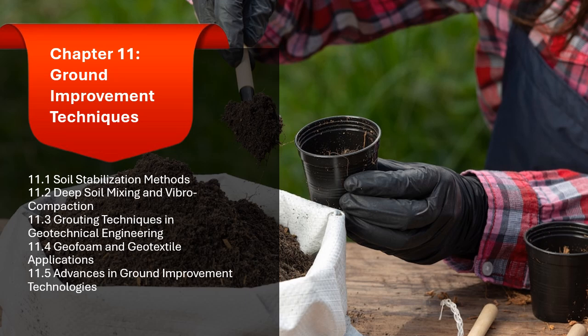Purpose. Lime stabilization reduces soil plasticity, improves compaction, and increases shear strength. Applications. Frequently used for road construction, embankments, and in regions with expansive clays.